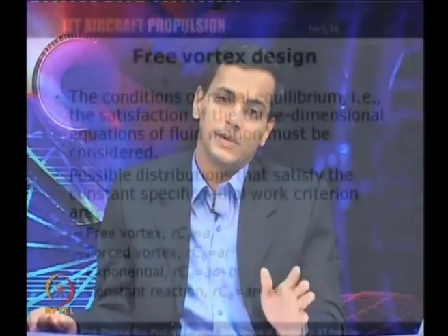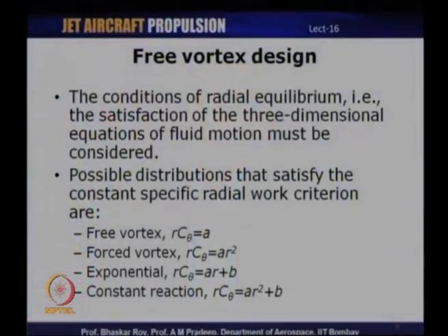and by using certain modifications to the free vortex design methodology, we can of course arrive at other methods of designing a blade. Now, what is important in all these methods is that we need to satisfy the conditions of radial equilibrium, that is, the 3-dimensional equations of motion need to be satisfied. That is one fundamental requirement in all these design methodologies.